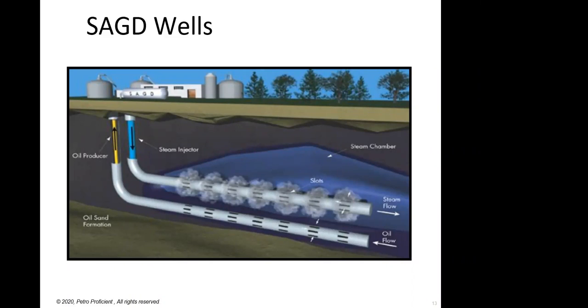are drilled, where you drill 2 wells parallel side by side, as can be seen. It's also called steam stimulation, in which a horizontal pair of wells is drilled in the oil reservoir, and the distance between the two is about a few meters. High pressure steam is injected in one well, basically the upper well, and this causes the heavy oil to become mobile and then flow in the lower well. This is a very advanced technique that is used nowadays as part of enhanced oil recovery methods.